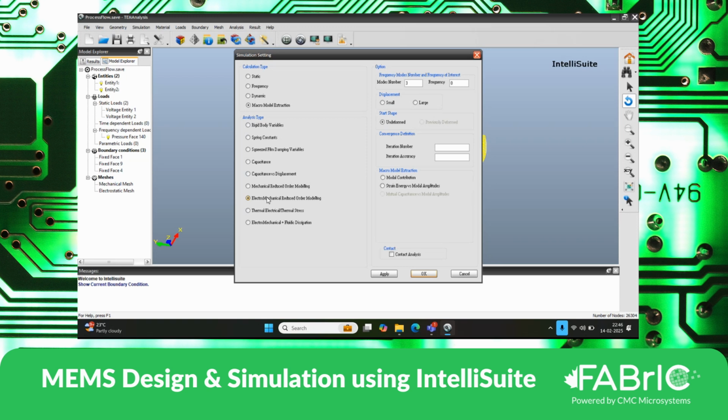In the case of frequency, we identify the modes of vibration, and in the case of electromechanical based simulation, we also do the buckling effect and things like that. I mean, let's park that aside. So the fundamental purpose of running the frequency analysis is to identify the natural frequency of different modes of vibration. Now comes the third one, which is called the dynamic simulation.